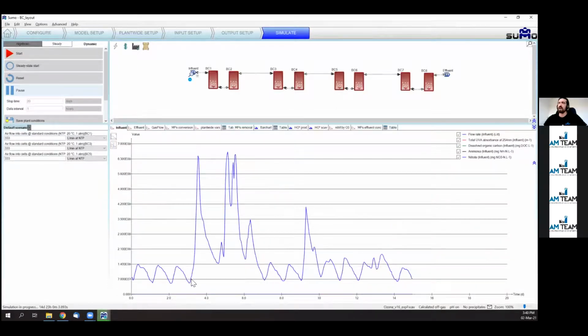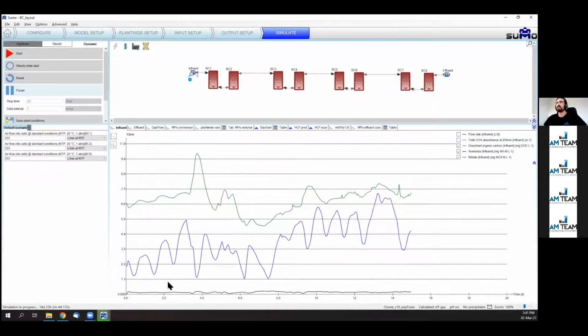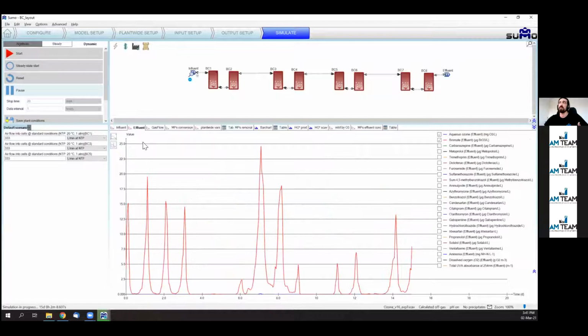And what happens in the dips? In the dips, sometimes the presence of ammonia helps knock down the bromate formed, as Wim anticipated, but sometimes the sole ammonia presence is not enough, because the matrix composition does not make the life of ozone and radicals short enough, and then having residuals for a sufficiently long time in your installation makes the bromate form.